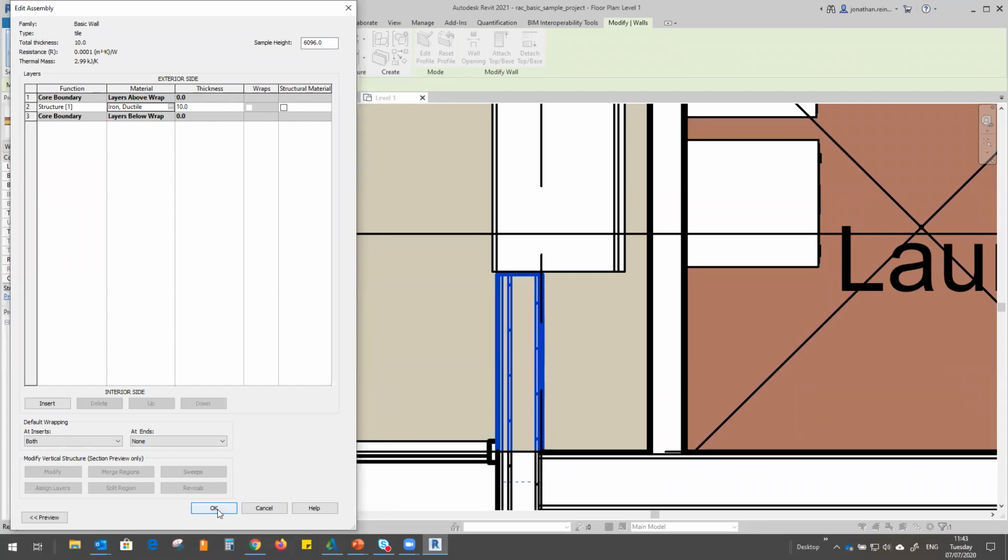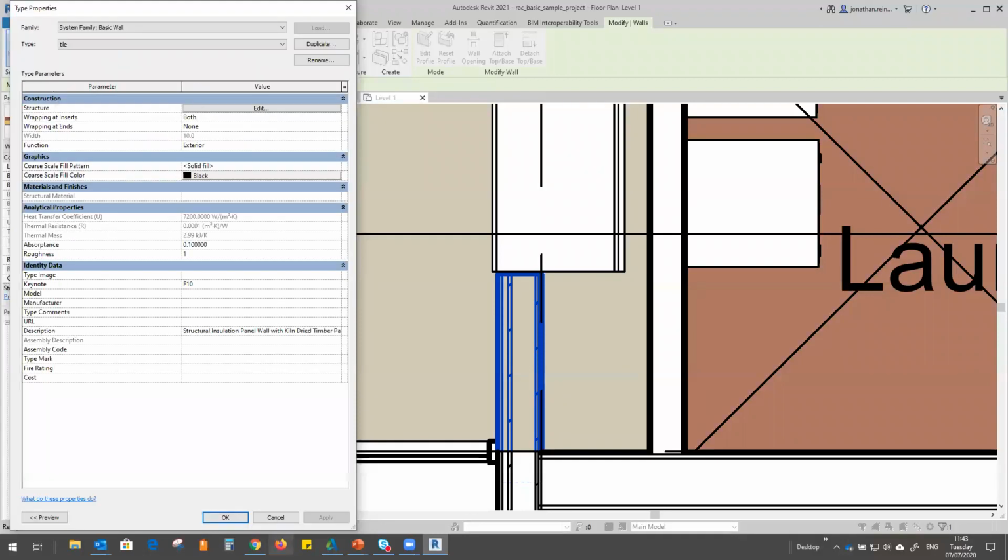I would be careful of doing that though, just because if you get a lot of different tile finishes, obviously then you'll need to manage them in the background as well. So it's kind of a balance between what can you notate instead of modeling, and then what do you need to model. So obviously, yes, if you are quantifying them for a particular reason, you may need to model them just in different sections. And then in front of this wall, you would just place a separate wall type of that particular wall as well. Thank you. I hope that answers your questions.